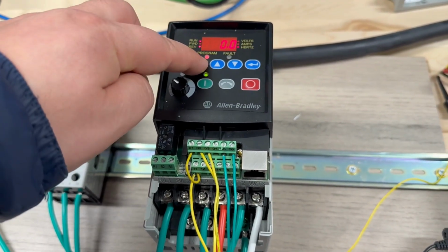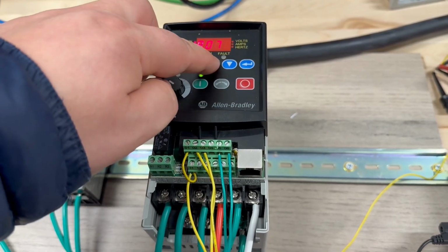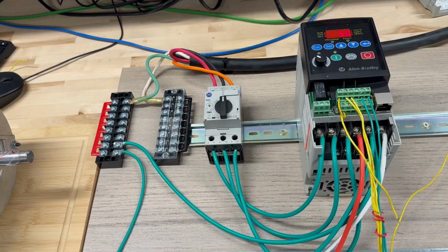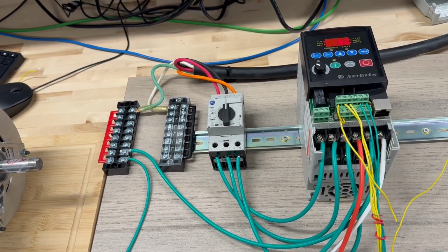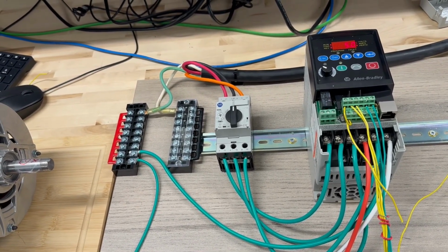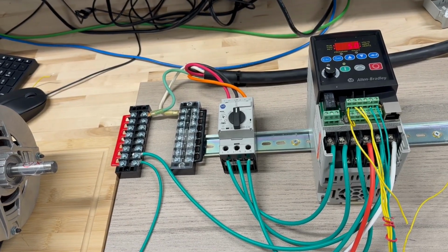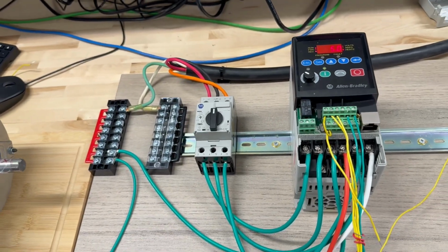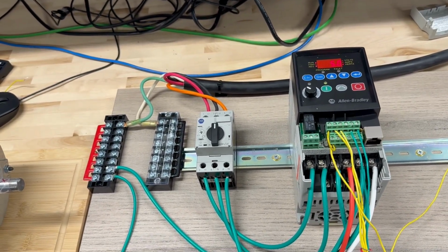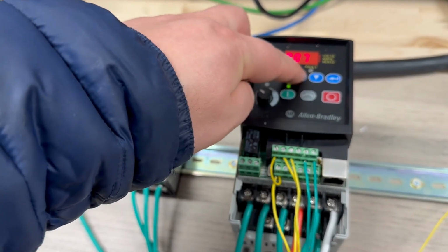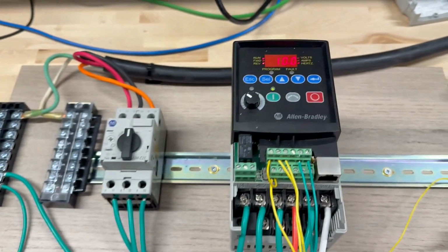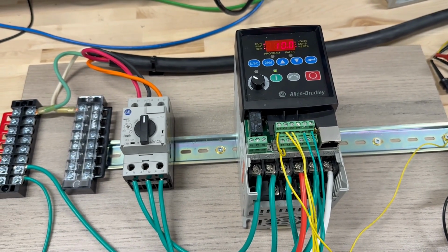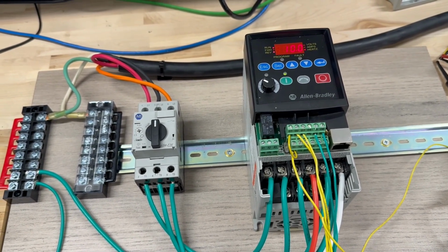A71 is 5 hertz. Whenever terminal 5 is 1 and terminal 6 is 0, it should give 5 hertz. For sure, you could adjust that later on. These are the defaults, we run with the defaults, then we change them later on. A72 is 10 volt by default. So A72 applies whenever terminal 6 is 1 and terminal 5 is 0.